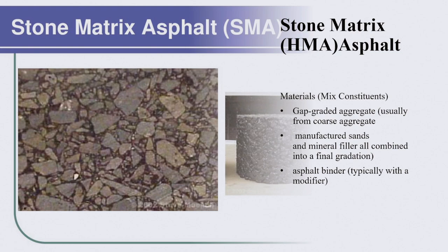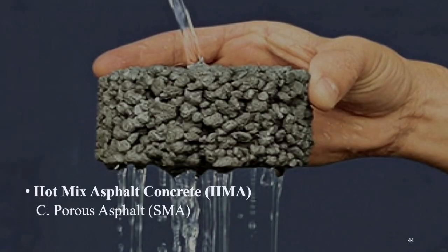Normally with a coarser aggregate, and remember this even in regular concrete mix design, if you add a lot of sand, you need to add a lot of water because the surface area would increase with a fine aggregate. Otherwise you would not have a workable concrete mix. Same thing here. So workability has to be a factor when you proportion your binder and when you think of adding emulsions to the mix.